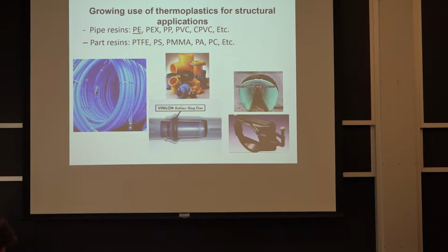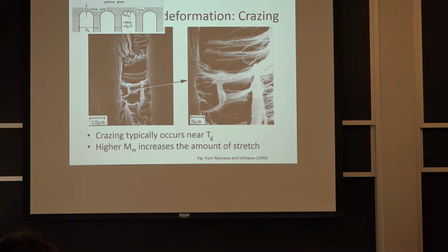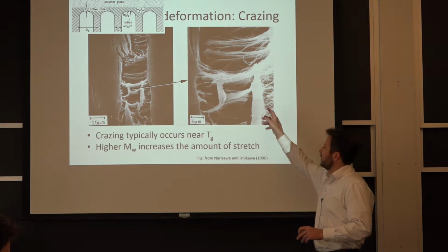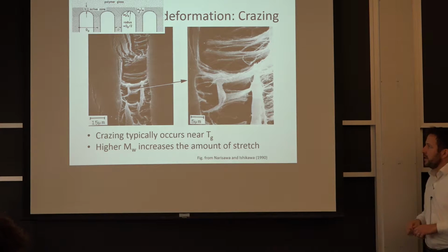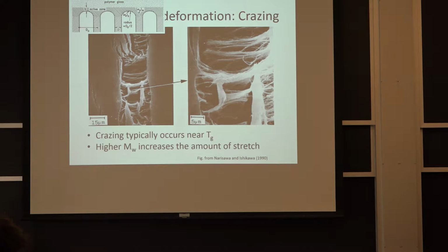But essentially, at this point, there are hundreds of thousands of miles of plastic pipes in the ground, all the way from relatively small, maybe even smaller, to 8, 10 inches that are just polyethylene, which is one of the softest of the polymers out there. Now, it doesn't come without some risk. So one thing we discussed again was that you can have local deformation. So instead of a crack here, you have a crack, but you still have ligaments. You have fibrils in them, and the stability of those strands varies a lot with the molecular weight. So that was a topic we discussed a lot.